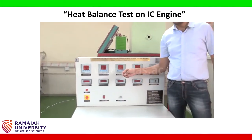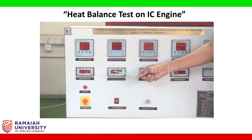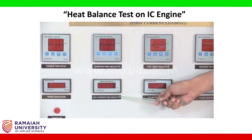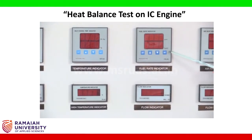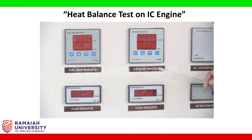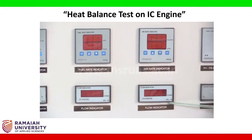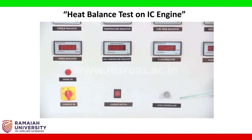This unit consists of a torque indicator, speed indicator, then multi-channel temperature indicator, then high temperature indicator which is going to measure the exhaust gas temperature, then fuel rate indicator, then flow rate indicator to the engine, then the air consumption indicator, then one more flow rate indicator which will measure for the calorimeter, then the loading switch, and the load controller.